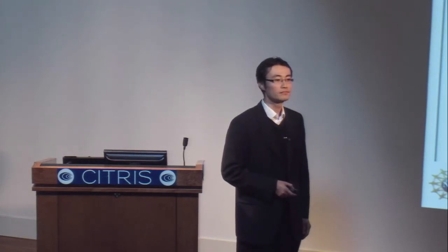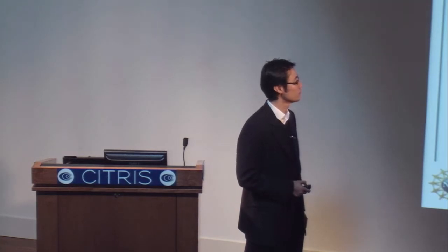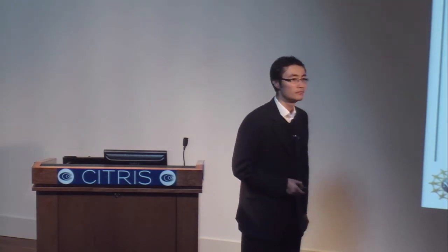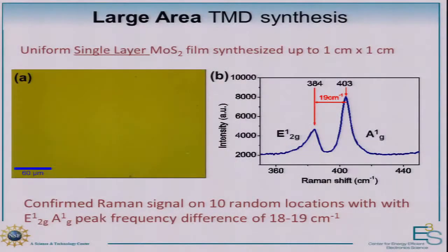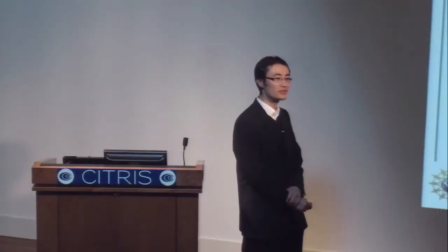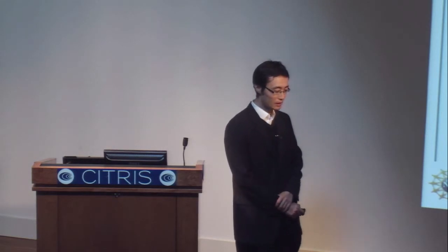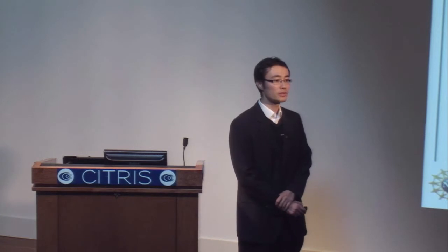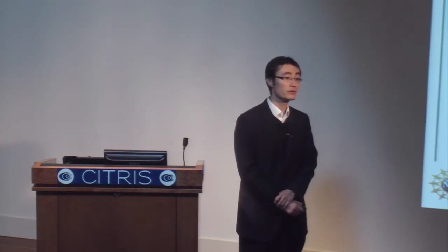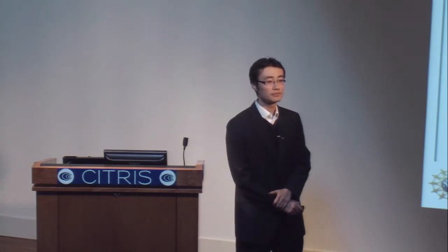Thank you. In particular, I'm interested in the CVD process that you used for large area molybdenum disulfide. Were you able to get a single crystalline layer, and how did you determine whether it's single crystalline? Of course not. It's such a large area. If you get a single crystalline layer, that's amazing. I think some of the records are about several tens of micrometer in grain size. We know it's polycrystalline. We are thinking of collaborating with the molecular foundry in Berkeley to look at the film quality and the grain size.